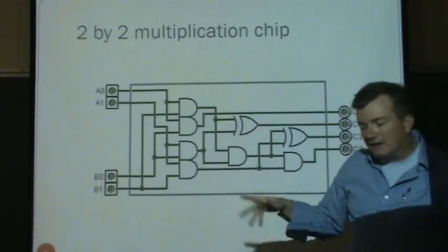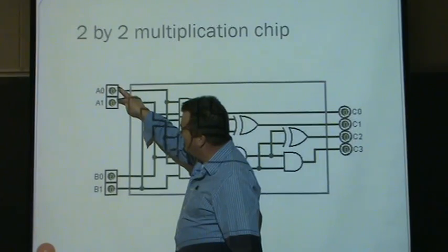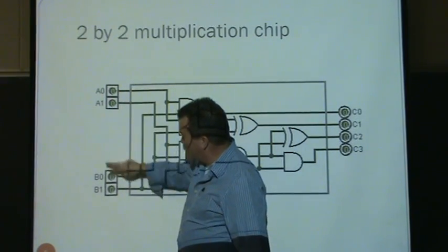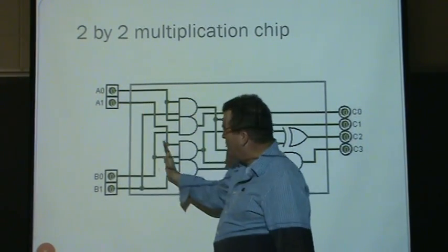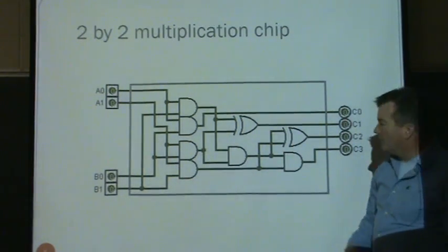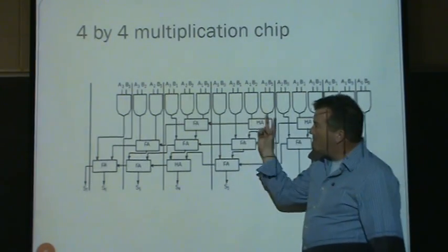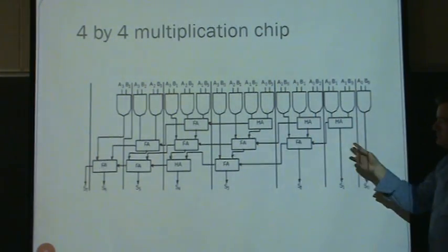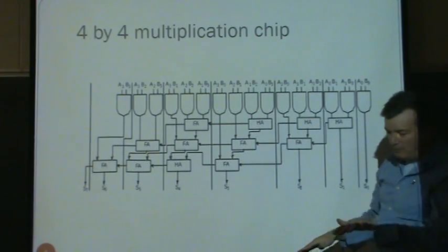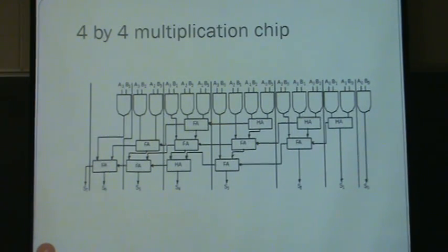You could work through the logic, but the idea is we didn't have to just take whatever numbers here, add it once, and then if this bit is on, add it again. We might be able to do it faster than having a ripple adder run twice. And then here's a 4-bit number times a 4-bit number, and then it ends up producing as much as an 8-bit number.